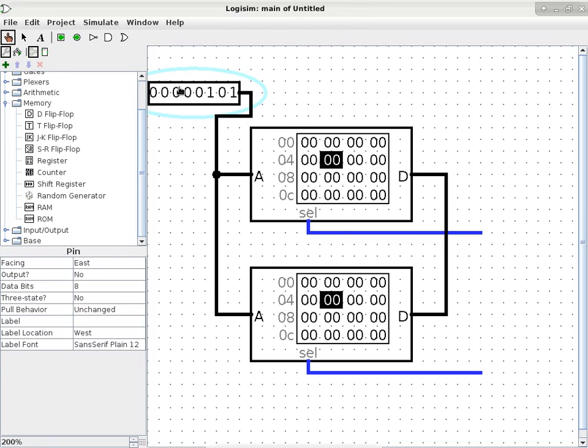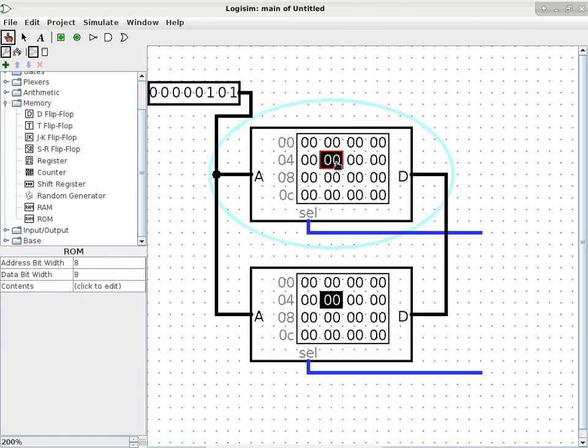Okay, so that is all good, except what is the actual output from the data port of both of these chips? And what I'll also do is something like this. I can change, you can also change the memory content of ROM in the simulator just by writing over it. Click the location and then just overwrite it.